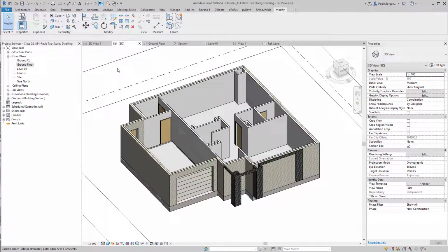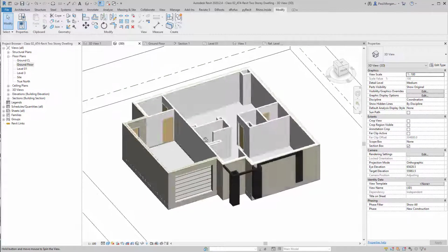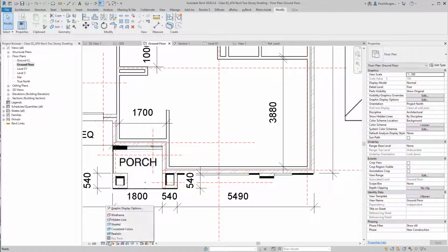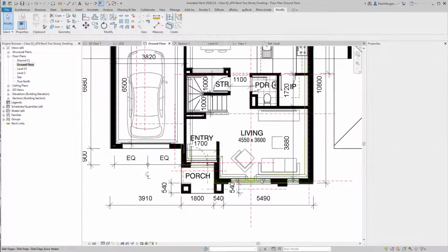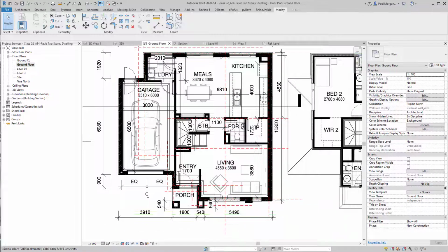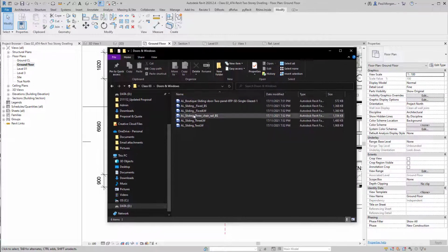So going back into Revit, I'm going to come over to my floor plan, and I'm again going to turn that into wireframe mode so I can just see the windows behind my floor plan. And I haven't got too many down here. And you'll find on Student Web, you've got a folder available to download which houses these A and L windows and door families, which we're going to utilize. And these are great references. Now, Revit does have standard windows built into it by default, but they're terrible. They're not very good. These ones are suited to our needs.